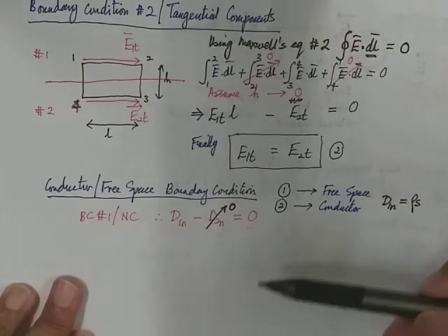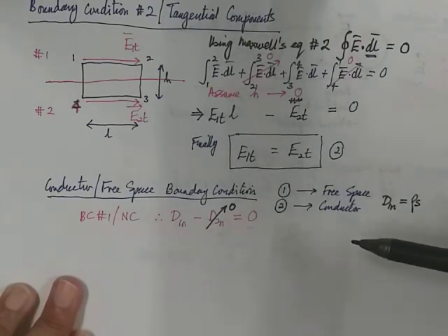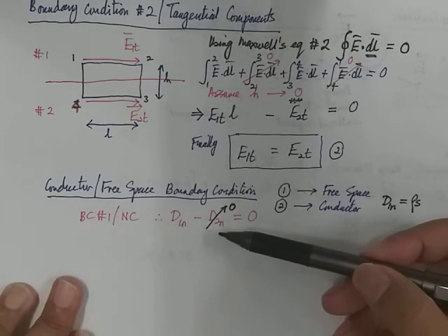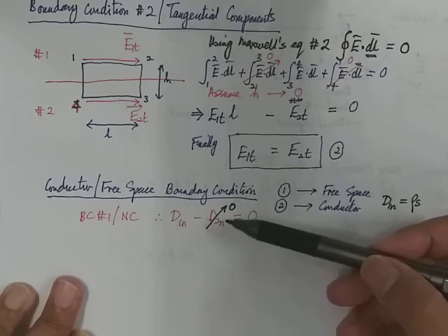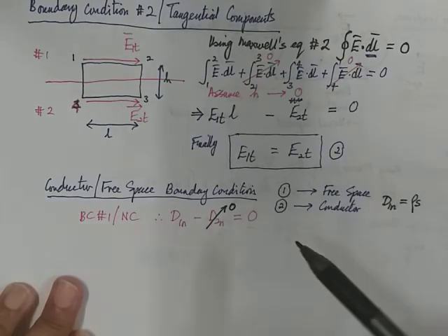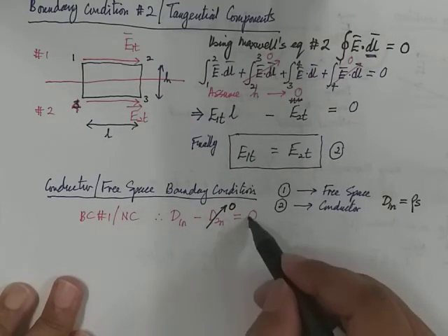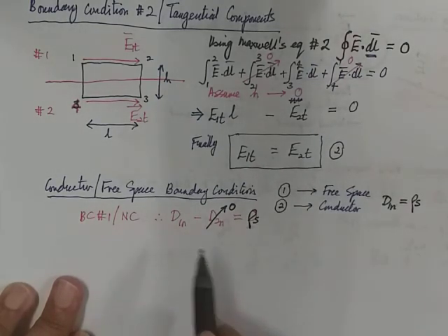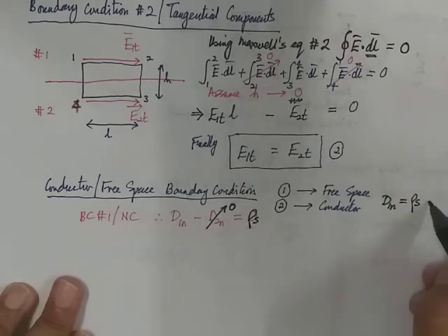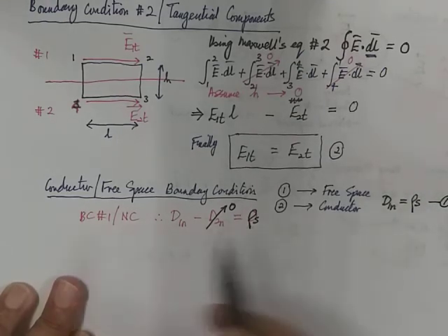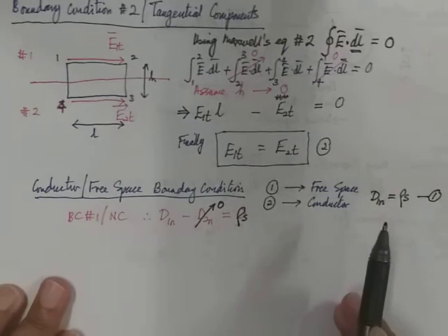Now we're going to relate that general medium to our specific medium, where we are assuming medium number 2 is made of conductor. And from our previous discussion, in a conductor, the net E is equal to 0, remember? So therefore, that will be the same here. The electric field in the medium of conductor will become 0. So the final equation that we have here should be D1n equal to rho s. So that should be our first equation for conductor free space boundary condition.